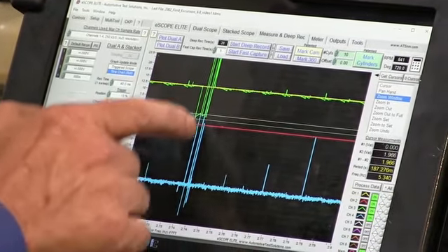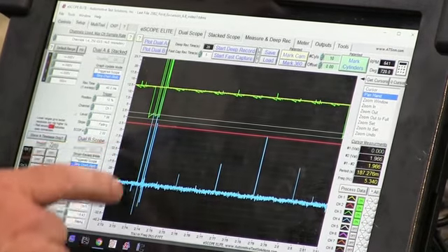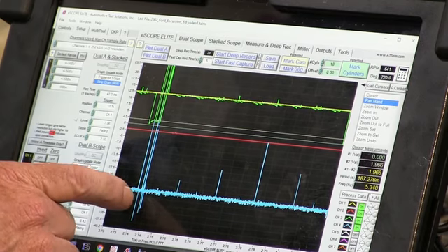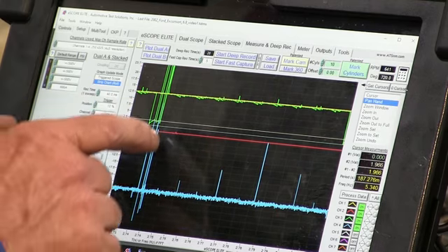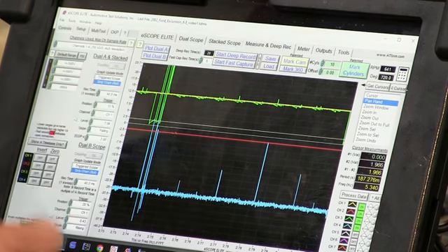See how big these are? See how small all these other coils are? Well, that's got a big hit. And to get that kind of a hit on the negative battery cable, that is a coil that's shorted on that cylinder, which is the number 9 cylinder.